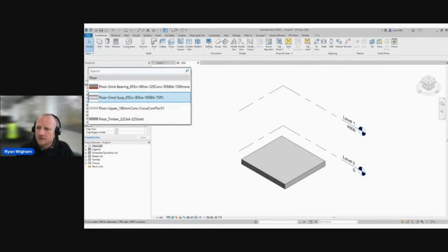The very basic principles of getting started on a Revit model, so beginning that process of those images we showed there, following your conceptual design, are going to involve something like system families. So they're objects that are built into the projects themselves. So you don't load them in; they're already there, and you just adjust them to suit your needs. So things like floors, so you can draw that floor in using the drafting tools.